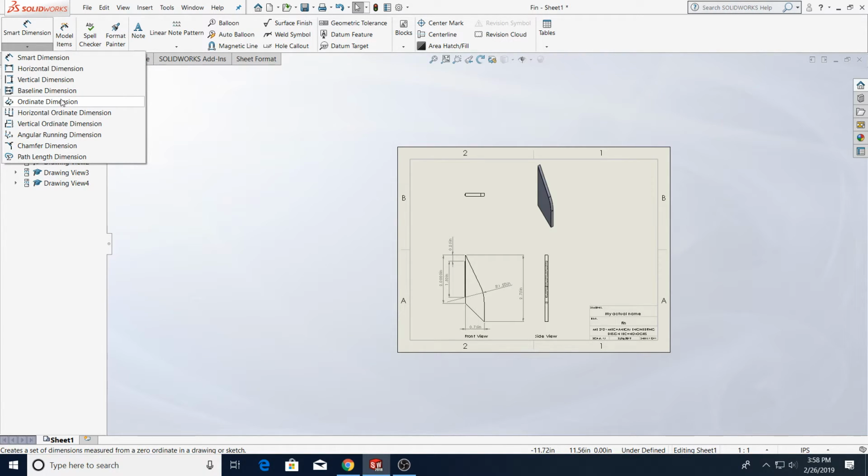In that case, you would define a datum point, and everything would be dimensioned relative to that datum point. Like you would say 1, 2, 3, 4 to indicate that this is 1 distance away from the datum point. This is 2 distance away from the datum point. Does that logic make sense?